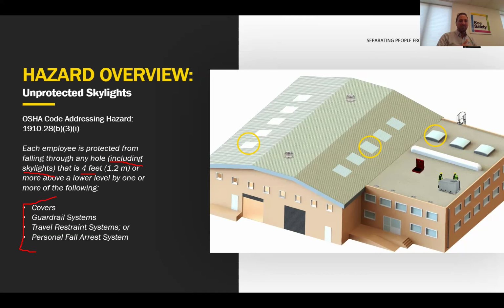What that means is if I'm designing a system that's in restraint, my connector, the thing that's tying me to the anchor, which is called a lanyard, is shorter than the distance between the anchor and the edge of the building. So basically, I'm on a leash and I'm tied off in a way so that I can't fall off the edge, right? So I always say, picture it like this. You're walking down the sidewalk and you hear a dog start to growl, right, on the porch. And you're like, oh man, this dog's going to attack me right now.